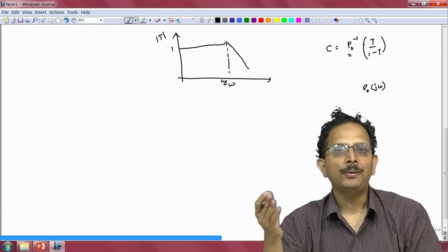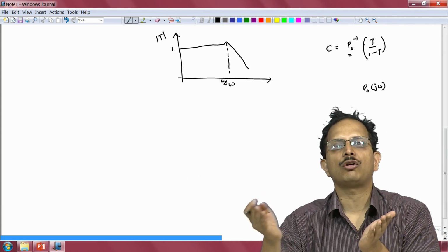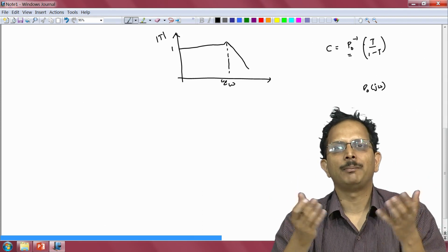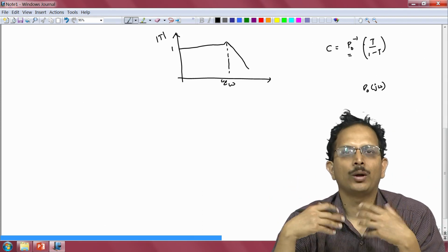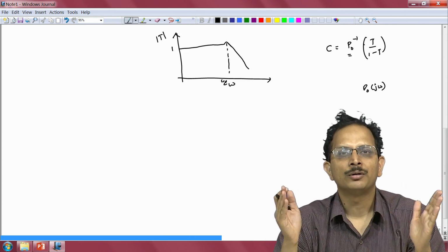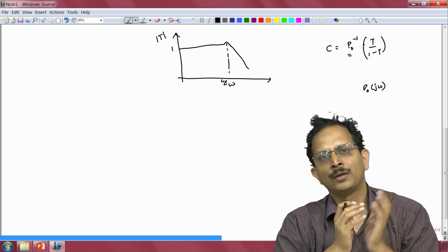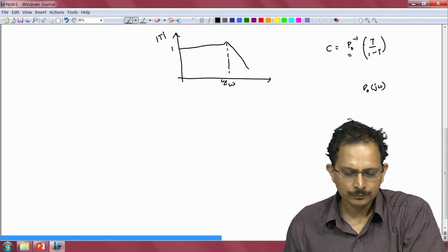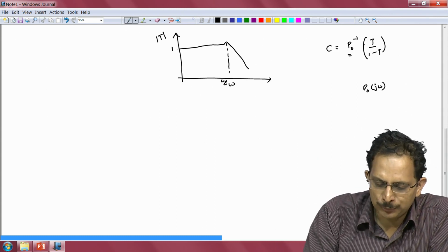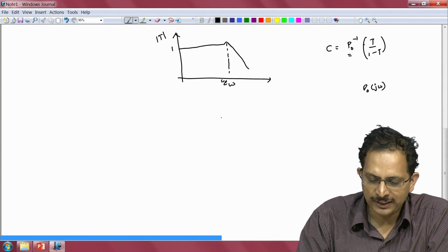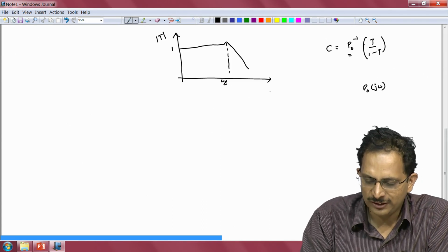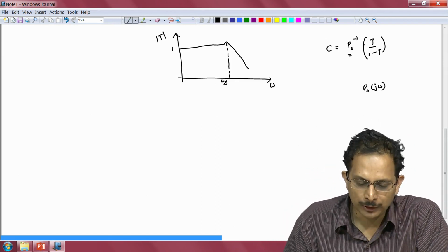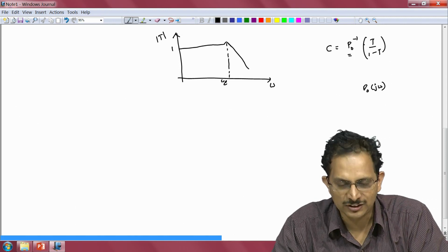As a rule of thumb, the upper limit could be approximately one order of magnitude beyond the bandwidth of the plant itself. So, that is the best possible bandwidth for the overall transmission function T that one can accomplish, provided we are able to characterize the model of the plant very well up to 1 decade beyond the corner frequency, the bandwidth of the plant. So, ideally we want our transmission function to be 1, but we now realize that it cannot be 1 practically for all frequencies. So, we have chosen to expect our response to be close to 1 up to some frequency omega c.